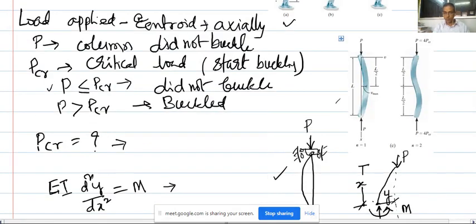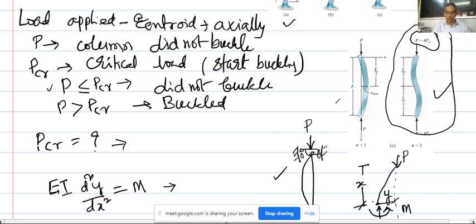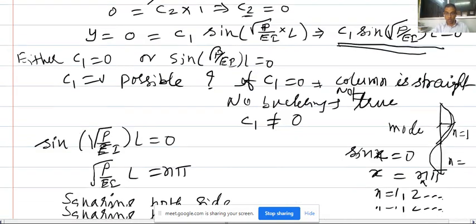What you are seeing here, this phenomenon, you will see only 2 loops when P is equal to 4 times PCR. That is what you can observe. Ask somebody to hold here, just a little bit, do not apply so much force with your finger, and you get 2 loops. Ask another friend to put a finger here, and you get 4 loops, that is 9 PCR. Like this it will go on. The load carrying capacity goes on increasing, anyway, that is fine.